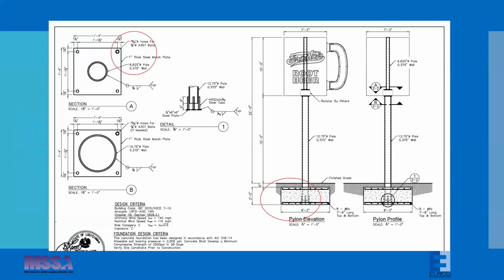In the upper left corner, I've got circled the diameter and grade of the bolts. That A307 material for the bolts is essential because our analysis is based on the grade of metal that is used in the bolts. So if you get a lesser grade of bolt, it may not actually engineer out. And so you may create a weakness in the sign structure that, because engineering drawings weren't followed, could result in liability if a failure were to happen.